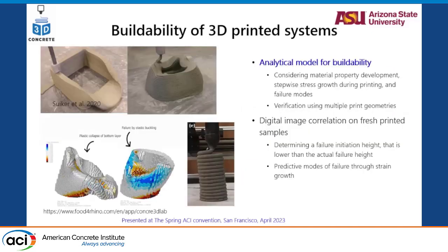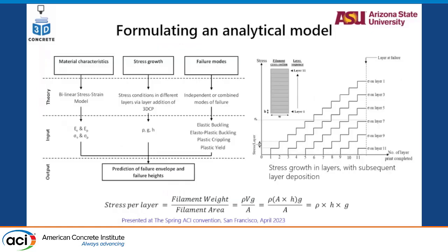There is a lot of modeling of 3D printing done there. But what we can usually see in literature is that cement mortar in its fresh state is characterized as an elastic material. Technically, the term elastic means that you could remove the load and the whole structure would go back to its original state before loading. But you can see that strains of around 5 to 10% are induced on those structures, which are not retractable, so it's more of a plastic. So the question came: is there an elasticity to the fresh concrete? Obviously there should be.